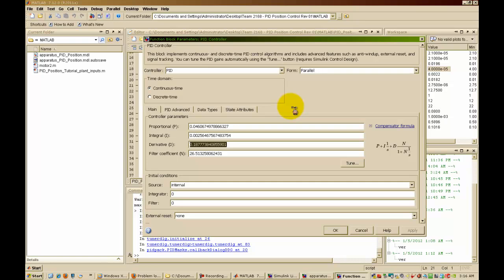If you notice oscillations in your response around any point, especially around your desired set point, your P is probably too high. So lower your proportional term and then see if that works out for you. If you're using another controller, be aware if it's ideal or parallel, because in the ideal case, changing your proportional term will affect the integral and derivative term as well. The controller that I provide is implemented using the parallel form.